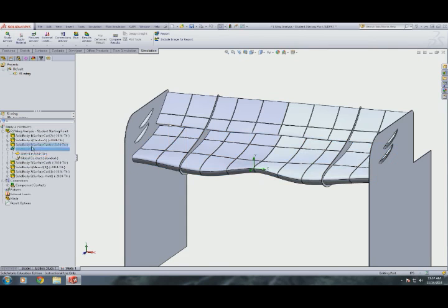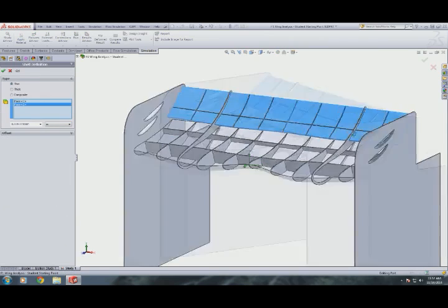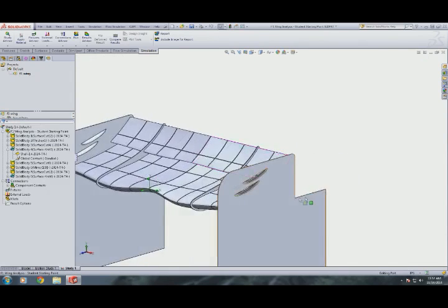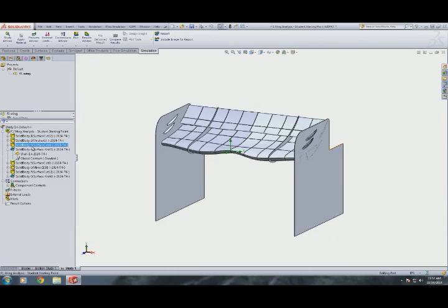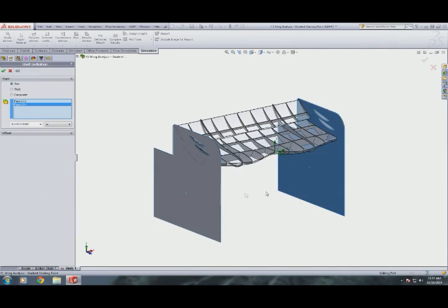So we're actually making it like a shampoo bottle, a real thin piece of plastic, or in this case, aluminum. If you want to enter in properties for carbon composite, you certainly could do that as well. So same thing up here, shell by selected faces, select top, top, bottom, bottom. I'll just set that to 0.05 to be consistent. Accept. And then I've also found that the end plates should be shelled out as well to get things to work nicely. So let's right click that, shell the inside of him. I don't think I'll always do both at once, but let's see if this will break.